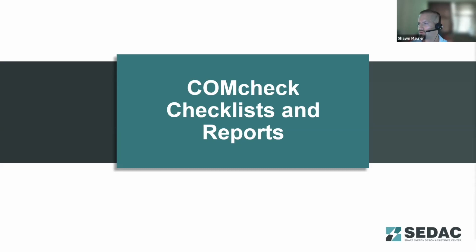usually for storefront windows, that's not a readily available number, as storefronts are usually done and assembled by component. There is an NFRC program, the component modeling program, where you would reach out to an NFRC approved vendor, and they do the total calculation for your U-factor and solar heat gain coefficient for the specific assembly of parts.